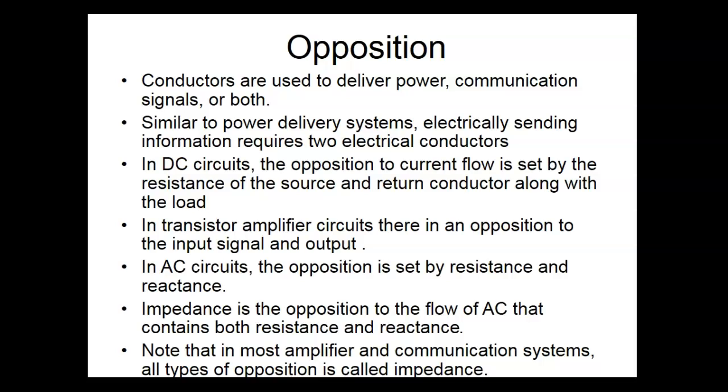So maintaining the frequency is basically more important than maintaining the voltage. We could live with a variation in voltage, but they can't have a variation in frequency because everything is set on 60 cycles. All the impedances, all the phase shifts, all the capacitors, all that kind of stuff that they have corrected for. All opposition is in ohms, period.